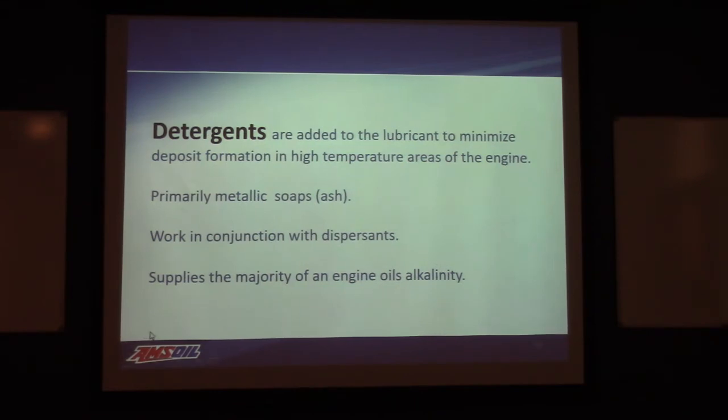Detergents also are our major source of alkaline material for acid neutralization. So oils that have a high level of detergents are likely to do better cleaning. They're likely to have a greater ability to neutralize acids.